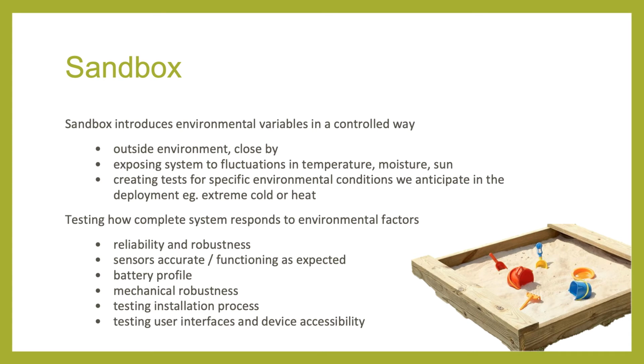In the sandbox, we're also able to test particular environmental conditions that will be in our deployment environment. For example, if we're deploying in a cold environment, we can put the device in the refrigerator. Although not technically outside, we'd still consider this a sandbox environment because we're testing an environmental condition versus basic reliability. The sandbox is also useful to get a sense of how easy an installation is and how accessible our device is once it's outside.